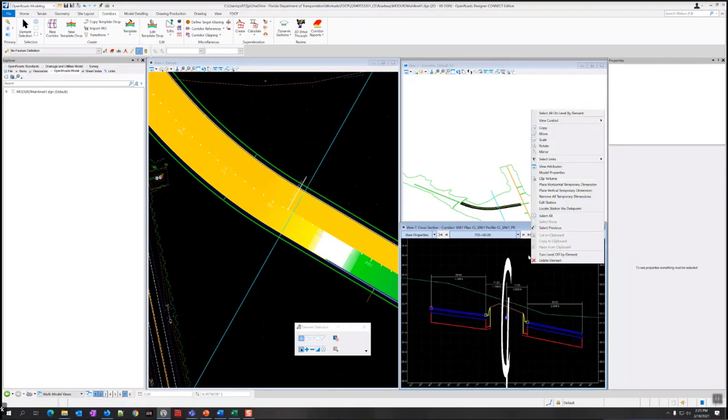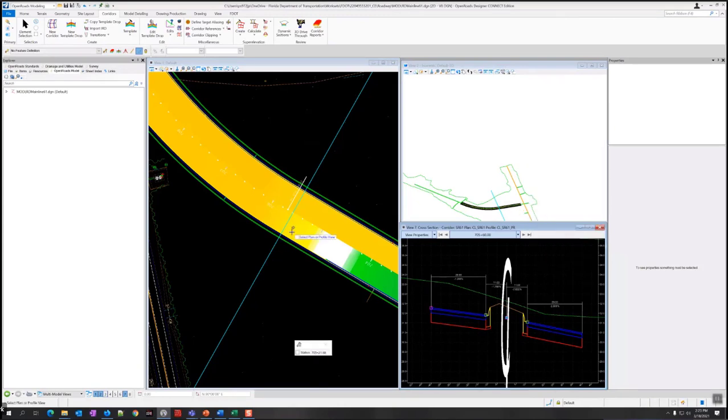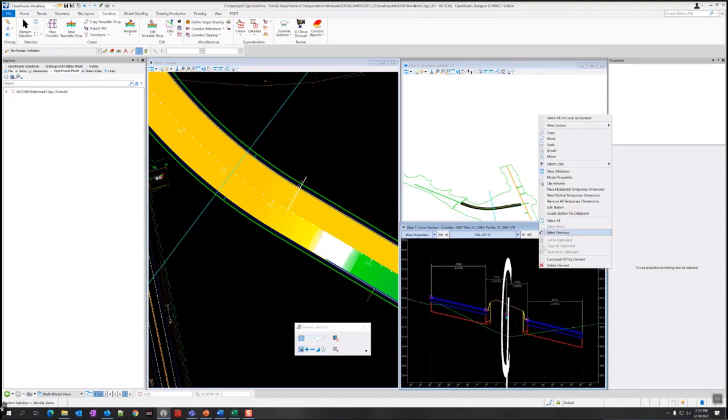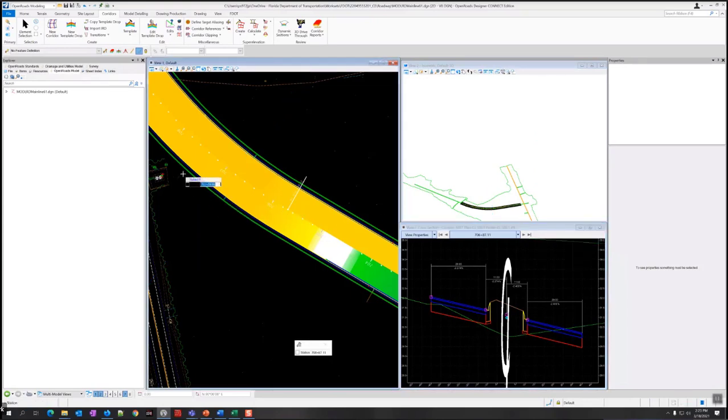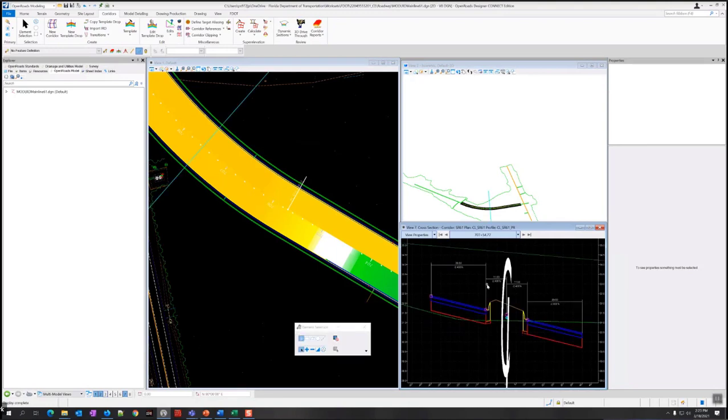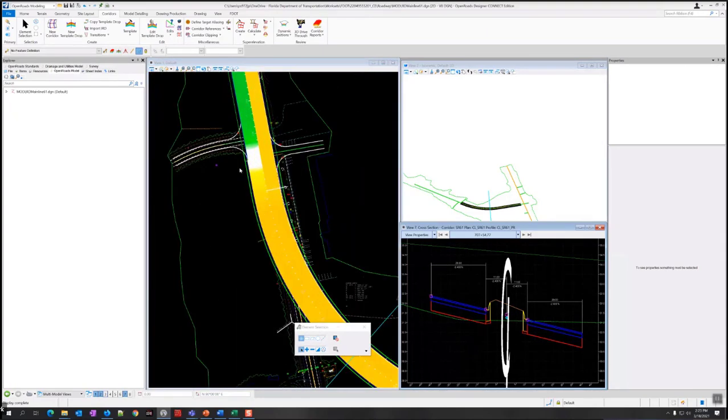So 1.26. Or I can right click and locate station by data point and just jump ahead here and make sure the full super is right. We're still not at full super. We come a little bit farther. It's almost a full super. There we go. Now we're at full super there. So that's helpful. You can check those numbers, make sure everything's working okay.